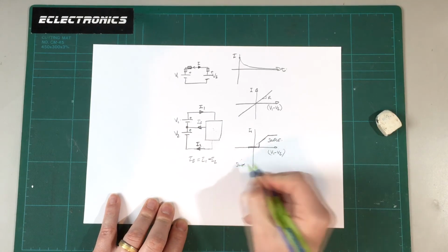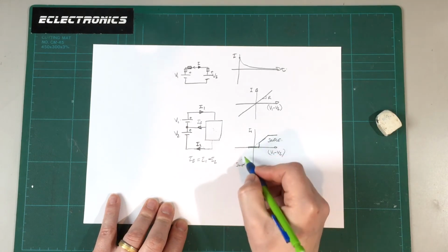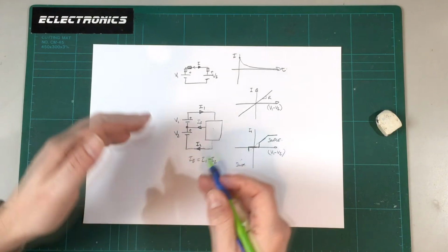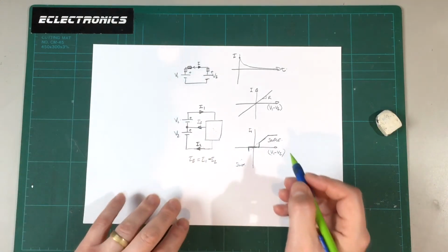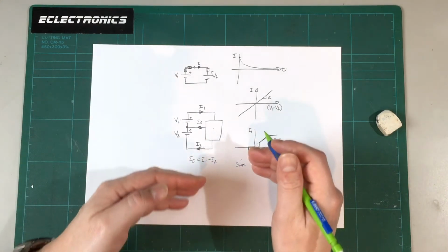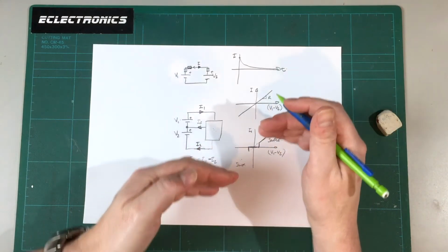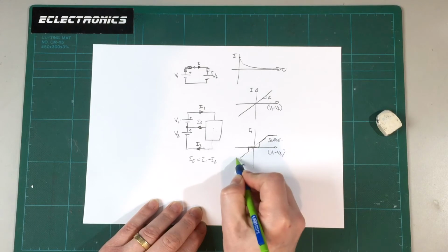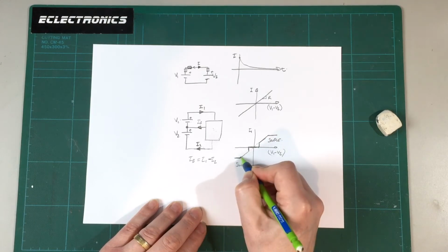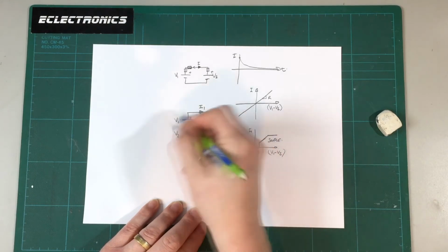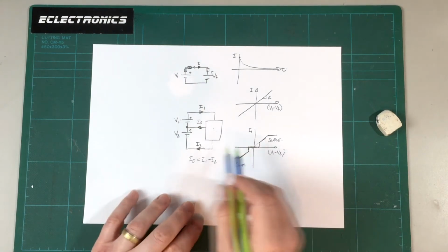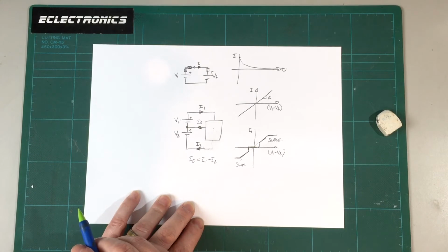So we're now in the sink part of the characteristic, but as I said before, we speculate it's going to be pretty similar because the voltages on the two cells are going to be reasonably similar. So the whole thing may be scaled slightly from one side to the other, maybe slightly different scales, but it's going to have a similar kind of characteristic with the current limit, again, limiting how much current is being put back into that cell. So that's the kind of curve we might expect to see with an inductive charge balancer.